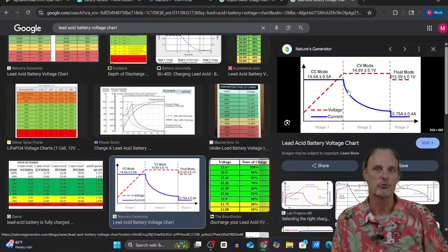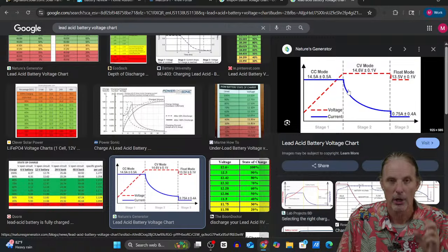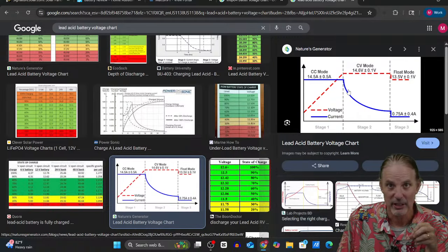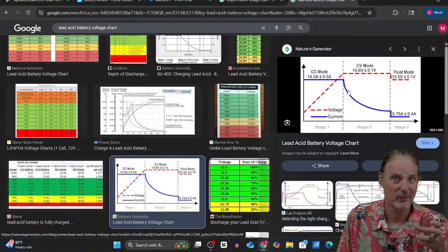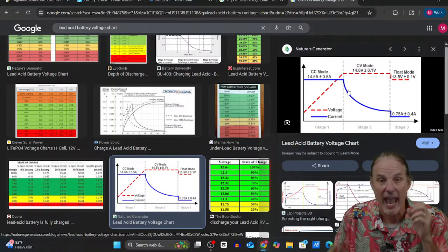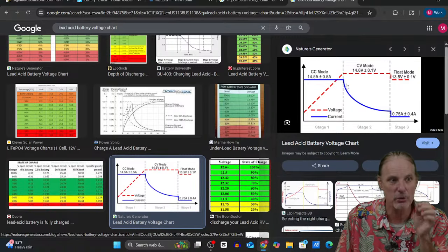So you drop in a lithium iron phosphate battery into your lead acid, and the state of charge of your lead acid reports that it's sitting at 80%, 80%, 80%, 80%, 5%. And you're like, whoa, what happened? Well, that's what happened, because it's measuring the voltage.